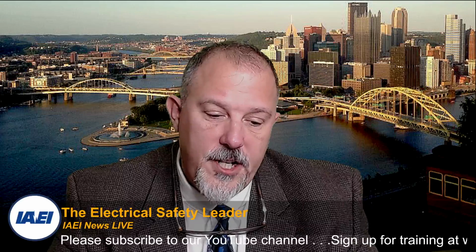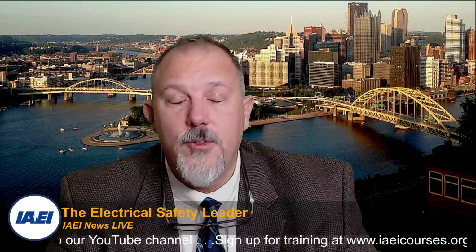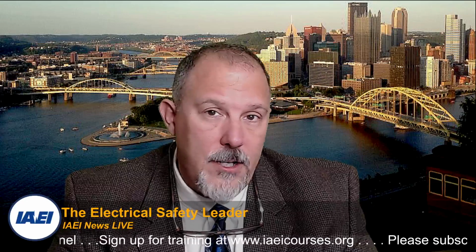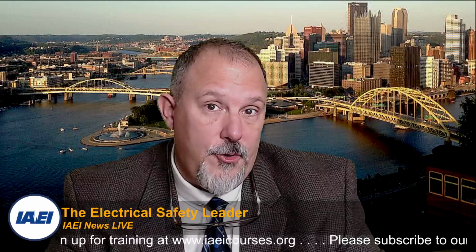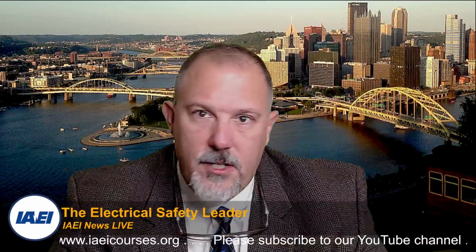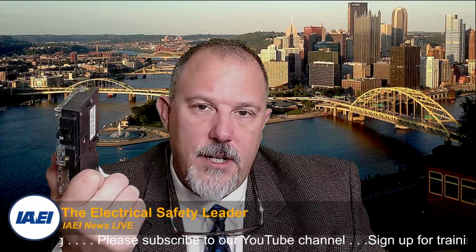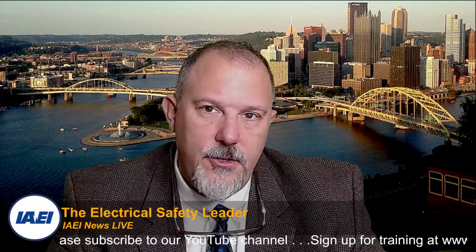So these devices function to provide GFCI protection. Do I need a neutral? Do I need an equipment grounding conductor? No, I don't. Remember, I don't need an equipment grounding conductor. I don't need a neutral. On the load side of, say, a 2-pole circuit breaker, I have a hot and a neutral, obviously, for my circuit. But if I have a 2-pole device, I don't need a neutral.